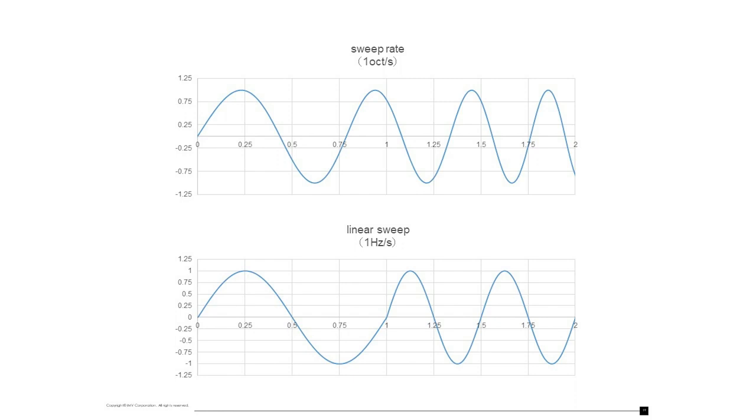In the case of the logarithmic sweep, it has the feature of sweeping slowly at low vibration frequency and fast at high vibration frequency, making the number of vibration wave cycles uniform at each vibration frequency.